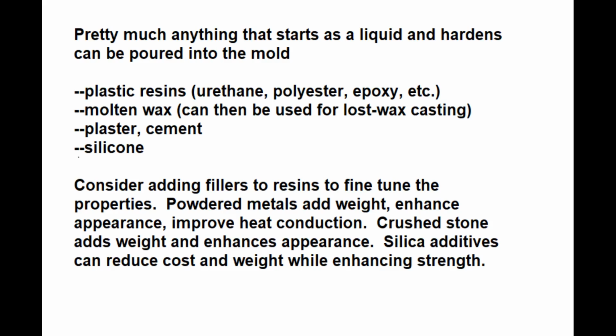You can also add fillers to the resin, so you can fine-tune the weight and the heat conduction, and if they're low-cost fillers, you can reduce the cost even further. So that's the background. If you're thinking this is the right process for you, let's dive into what you need to decide when you are ordering your mold.